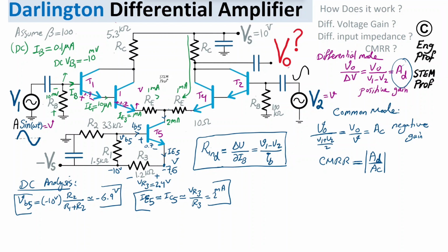Let me write it clearly so that there is no mistake. Negative 1.41 volt. And we have 1 milliamp going through 10 ohm. So that's another 10 millivolt, so plus minus 10 millivolt. That means this node finally is minus 1.41 and minus 10 millivolt. This node is finally the voltage of the emitter common node, whatever it is, minus 1.42 volt.